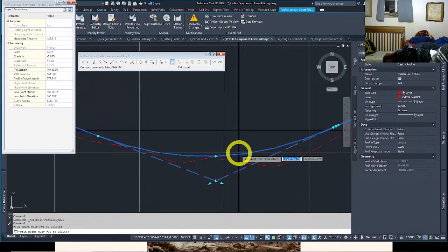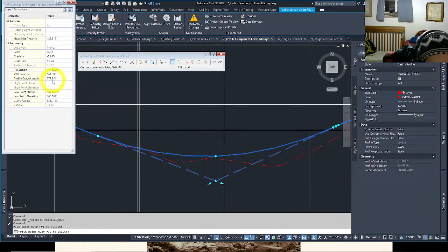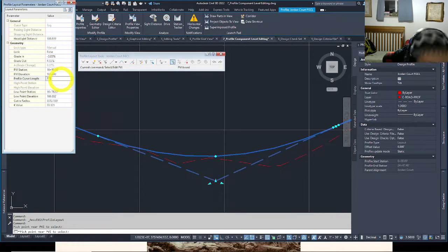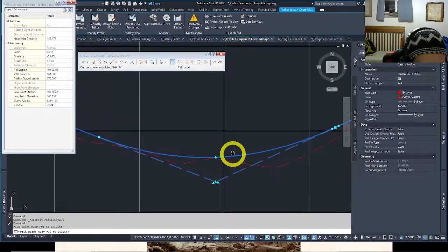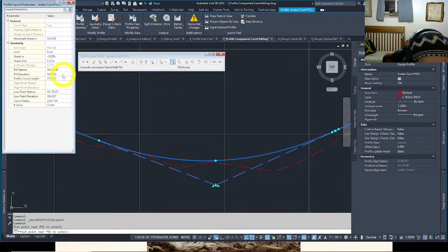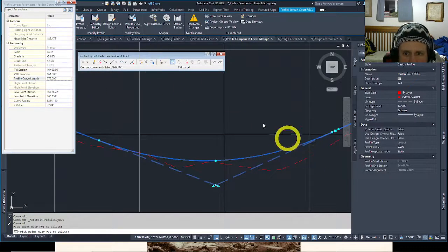So we're just going to change one thing. We're going to change the profile curve length, this method, 275, instead of that oddball number. It shrunk it just a little bit. It shrunk it evenly on both sides in a way. So now we have some more even stuff. The profile curve length, it depends on what our parameters are. We try to mess with this stuff as best we can. Something's usually got to give, and mathematically, something's going to be an odd integer or decimal fraction. You can get a couple of two out of three things, let's say, to even numbers, but one might have to be not at an even decimal place. So you do the best you can there without losing your mind on the math of these curves.